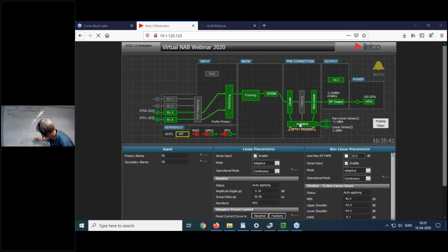That means the distance to the noise floor increases, and the distance to the noise floor is what we in digital modulation call the MER. The analog people would call it carrier-to-noise, kind of similar. So using this noise distribution technique, we can actually improve the MER of the signal.